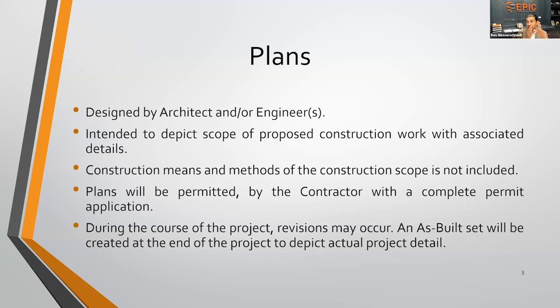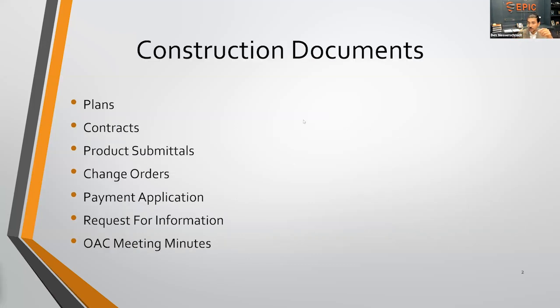But there'll be several different revisions, and even revisions as a request from the review board at the municipality that would effectuate that. And you'll see multiple, and those are going to be called construction sets. Construction sets with revision numbers, and on the title block, you'll see revision 1 with such and such date, revision 2, such and such date, so on and so forth.